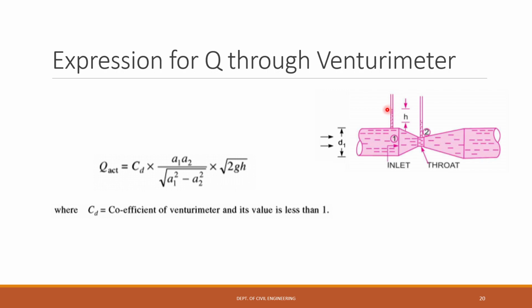Okay. So this height is measured, and this height is related to the pressure inside this pipe. Similarly, at throat also you can see that liquid level is increased inside the piezometer. Up to this level you have the liquid in the piezometer. So this height will give you the measure of pressure at this particular point, at 2. Okay. Now what is H? H is the level difference between the height of liquid in the piezometers connected at section 1 and connected at section 2.